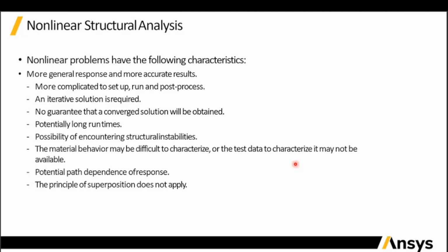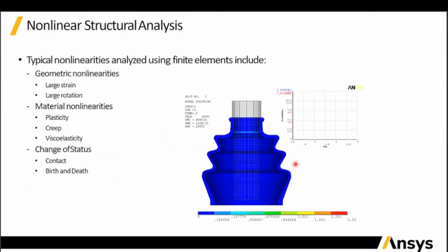Whenever you are doing a nonlinear structural analysis, the material behavior may be difficult to characterize, or the test data to characterize it may not be available. So there will be the potential path difference of response while doing a nonlinear structural analysis. And the principle of superposition doesn't apply whenever you are doing a nonlinear structural analysis.